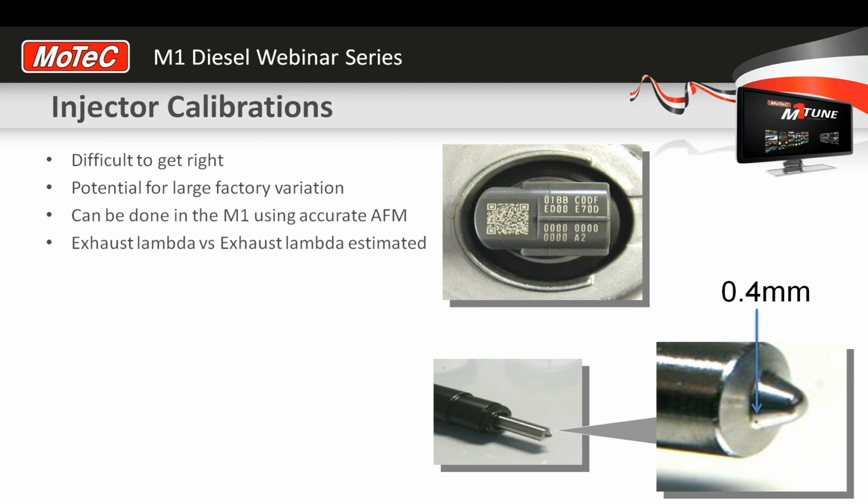So the process is that manufacturers produce the injectors and then individually calibrate them and give them their own linearization code for the flow characteristics of that one injector. Each injector produced has a different flow amount, and the flow amounts can be significant from one injector to the rest.